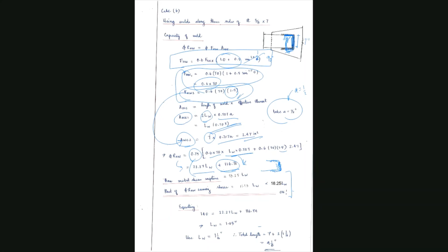You need to only consider the failure around the opposite welds. You do that, you see that the strength of the base metal from shear and yielding is greater than the strength of the weld. Now you are in a position to easily substitute all of them to phi R_n,w equals T ultimate.